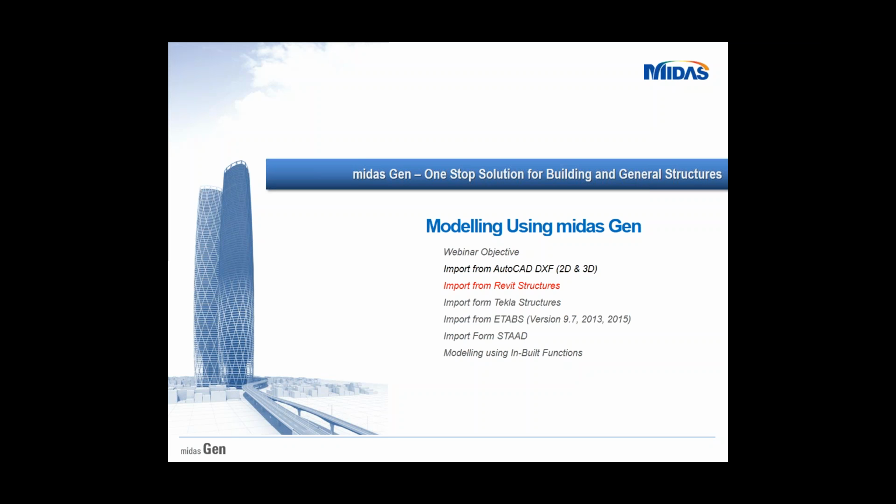And another question from Mr. Livy QNO, how can arc elements be manipulated in importing to MIDAS from DXF? Sir, arc elements, we need to break them into smaller parts, either by using the explode function, or we need to break them into smaller parts: arcs, circular elements, curved elements. These need to be broken. So once you break them into small parts, you can take them in here. Yes, sir, arc to multiple lines. You need to convert the arc into multiple lines.